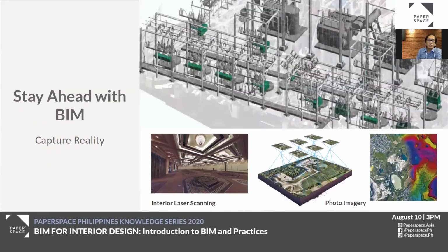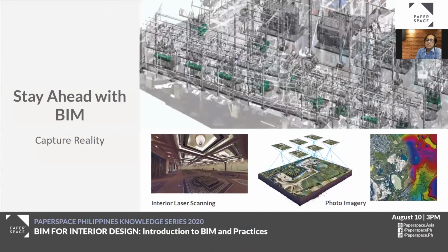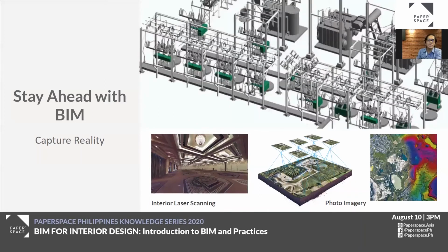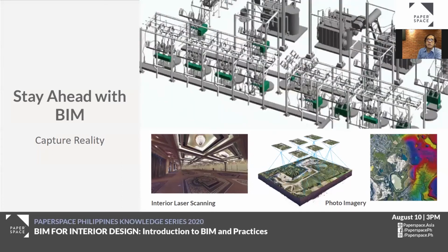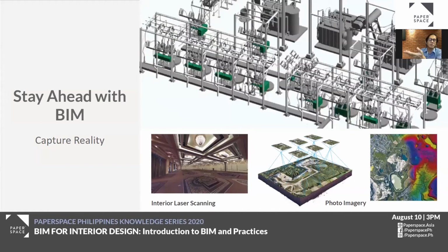Same with photo imagery for large-scale site surveys. It creates stitched images to generate a model. So it's like taking a lot of pictures for each particular area and combining them to generate a 3D model. Way back then, they usually used planes or even helicopters to survey the area. But now, recently, they've been using drones as another means of surveying, saving preparation time and cost. This is very handy for time-constrained projects, and you need essential site information data, like slopes and other site conditions.